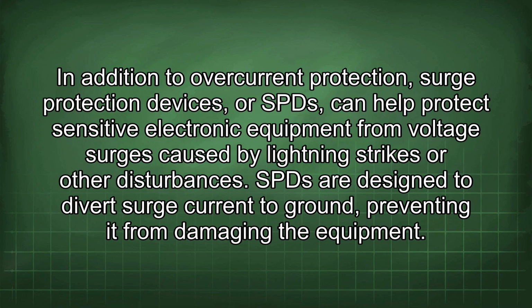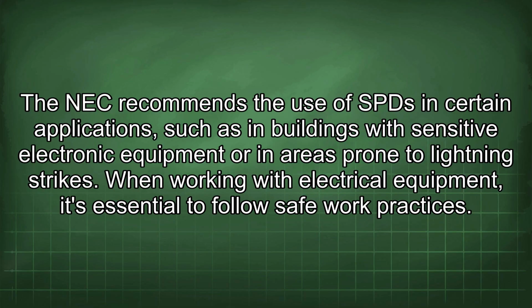In addition to overcurrent protection, surge protection devices, or SPDs, can help protect sensitive electronic equipment from voltage surges caused by lightning strikes or other disturbances. SPDs are designed to divert surge current to ground, preventing it from damaging the equipment. The NEC recommends the use of SPDs in certain applications, such as in buildings with sensitive electronic equipment or in areas prone to lightning strikes.